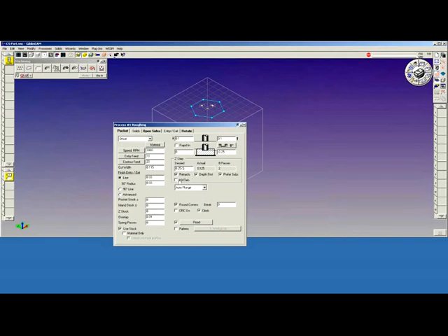Hit flats is an option for solids machining. Round corners should always be turned on, regardless of whether you're doing a corner break or not. If you're not doing a corner break and you want sharp corners, make your break 0. But round corners gives you a cleaner tool path. It tends to drive the cutter around corners instead of bypassing the corner before it changes direction. So you get a nice cleaner cut around the corner.